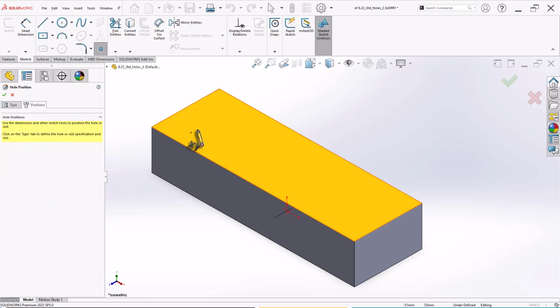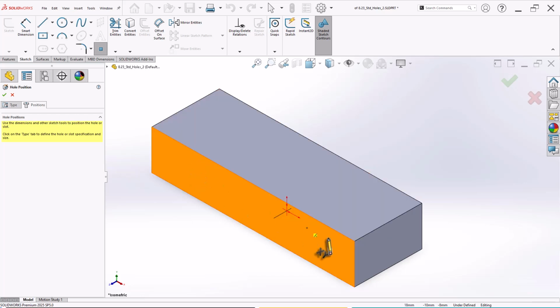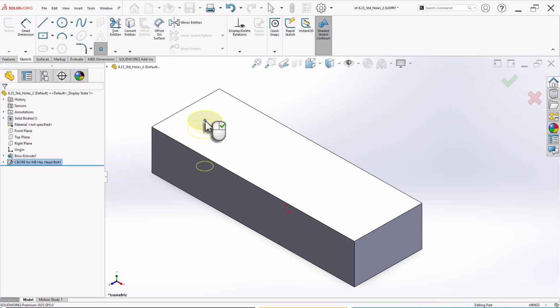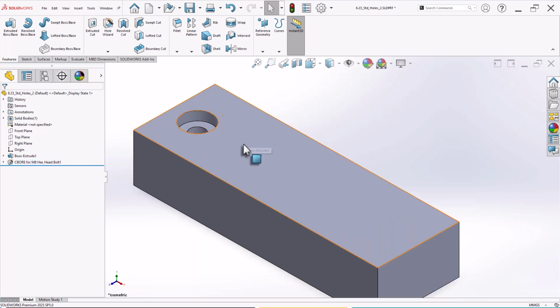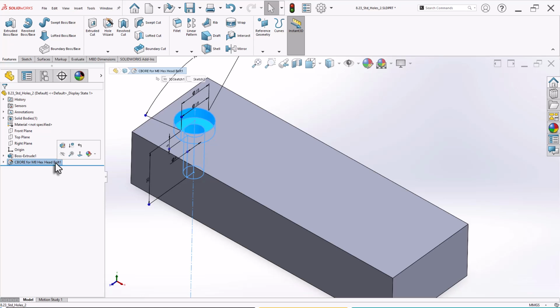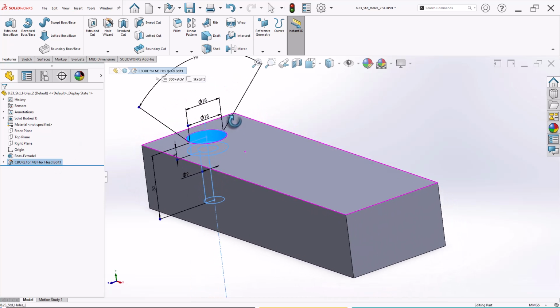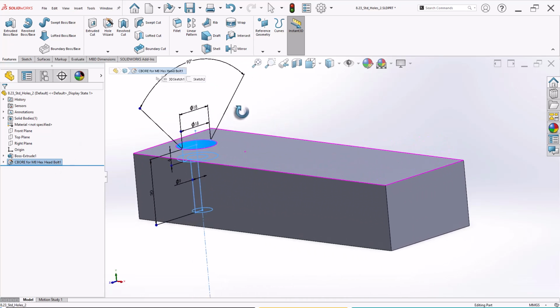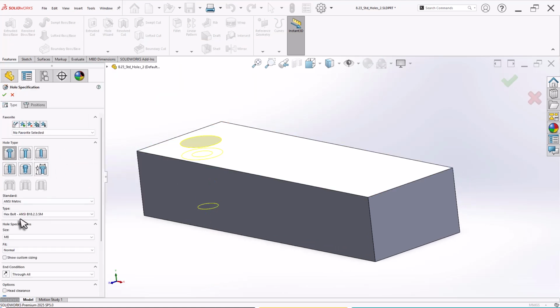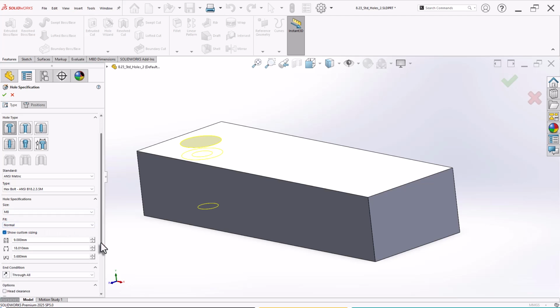and 3D sketch. Now let's place over here. 3D sketch allows us to create holes on this surface and this surface. If you choose 2D sketch, you can only go in one direction. So let's click. Now right click. So I have placed a counterbore of the selected size. Now the moment you select that feature, you can see the sizes. If you require some changes, just go ahead and edit the feature and activate the show custom sizes, and you can modify this if you require.